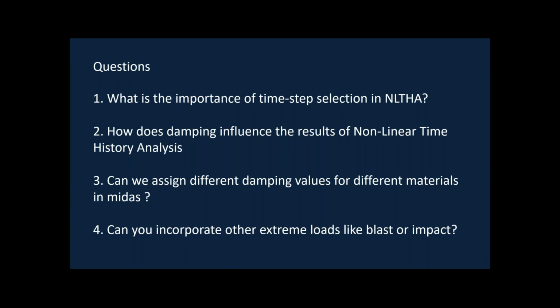The second question is, how does damping influence the result of a nonlinear time history analysis? In nonlinear time history analysis, damping plays a very important role, and there are various methods to specify the damping for our structure. Generally, engineers use the modal type of damping. However, the modal type of damping should not be used in the case of nonlinear time history analysis.